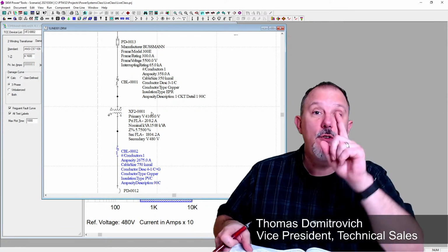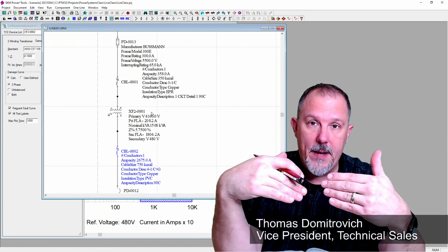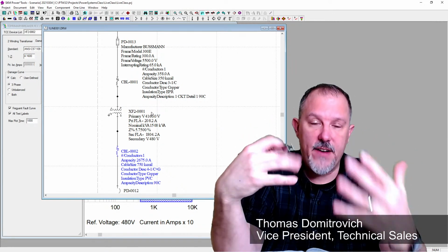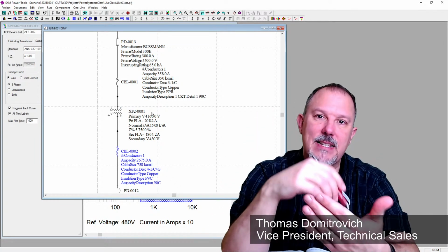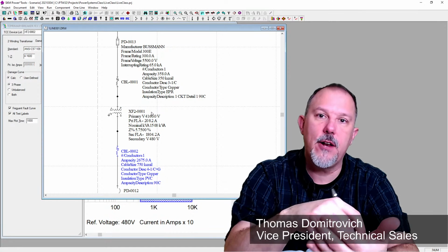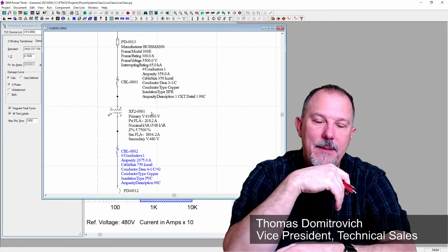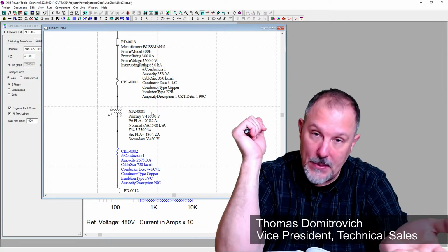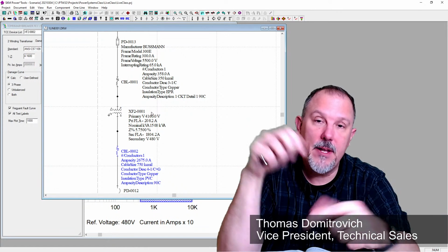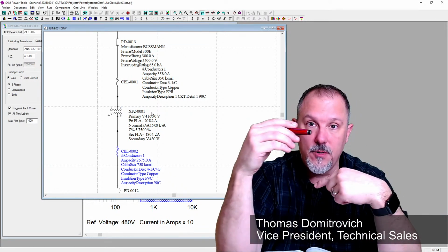All right, but you understand what we did. Just go back here. We have 5 conductors in a raceway. When you do your ampacity adjustments, you can do that off of the 90° C column. The mistake I made, and it's just been a long day, and we're all prone to mistakes, was I used the 75° C column when I did my backwards math.